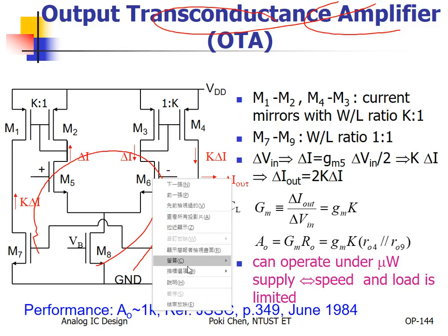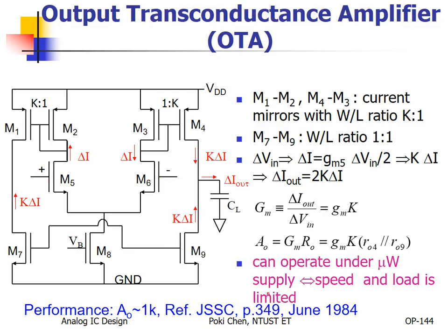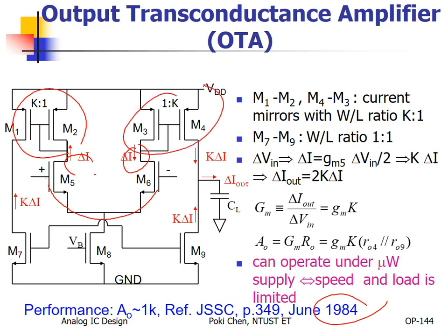All right. So the idea is, again, more than 35 years ago, very old, right? We convert the input voltage into output current. Then we apply a current mirror to enlarge the output current. Okay, so 1 to K, K much larger than 1.